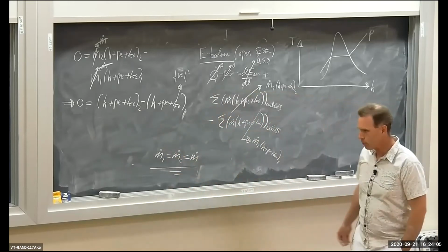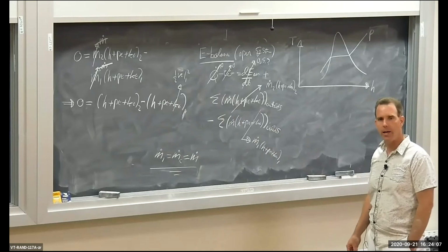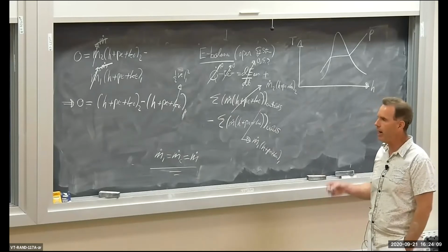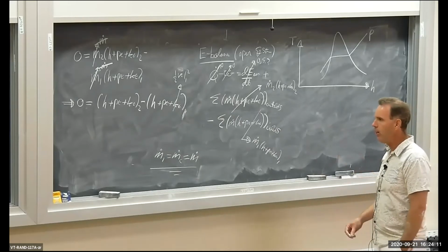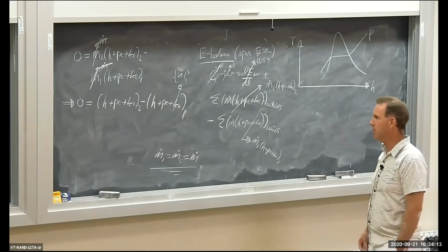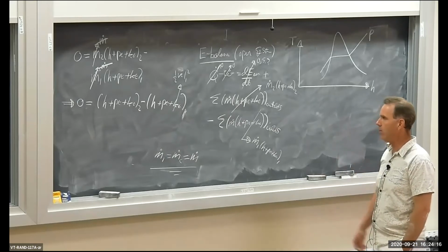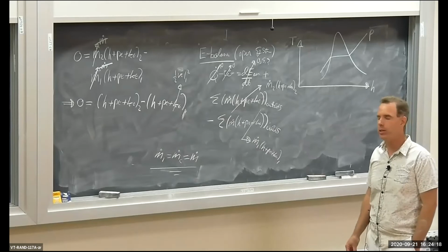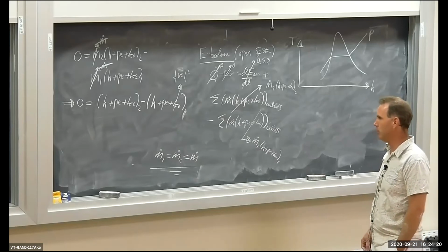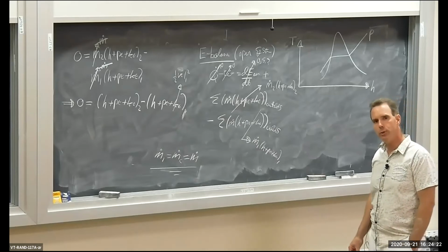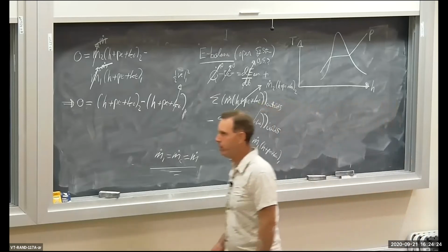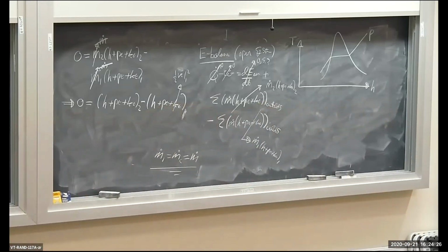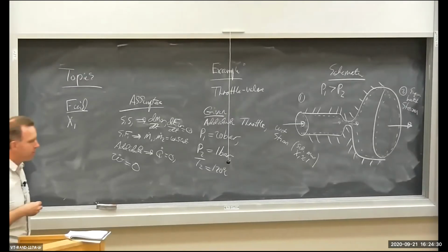Now, we're not given any information about the inlet and the outlet velocities. I don't have any flow areas. I don't even have any m dots. So I cannot calculate any of these inlet and outlet velocities and therefore specific kinetic energy terms. So I'm going to assume them away. I have no information on the inlet and outlet kinetic energy or velocities of the flow.